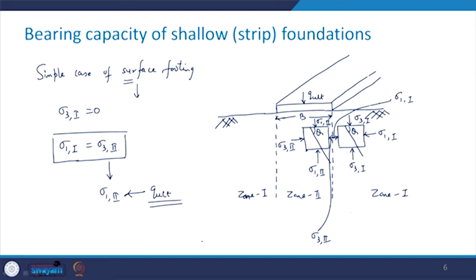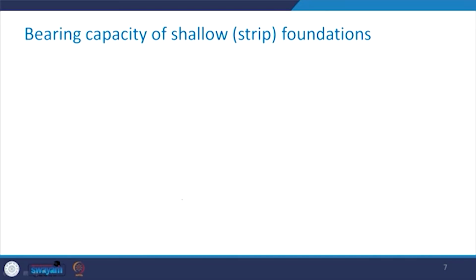Let us see how we can do that. First, we will calculate the strength of material in zone 1. So, I write it as part A, that is, calculate strength of material in zone 1. Now the first one is going to be the strength of the rock material, because it is a rock mass. So rock material and the discontinuity both will come into the picture.